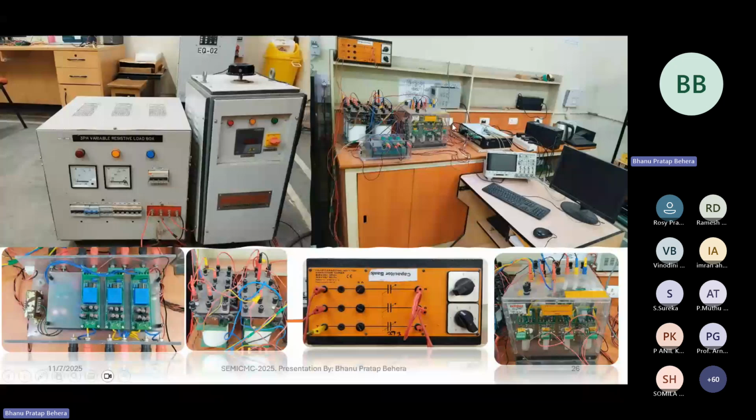Outside, if you see, we have this auto transformer. This is the 3-phase power supply. Then from here, the output is coming inside this Semikron inverter. We have the rectifier module, which is converting 3-phase AC to DC. Then from this DC we can convert into AC. If you give the pulse, here we are giving the pulse, then it is converting into AC.